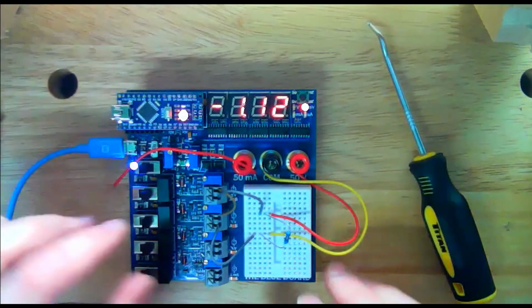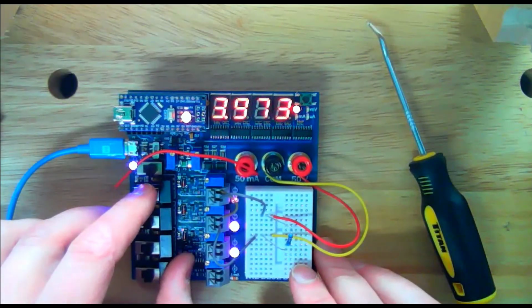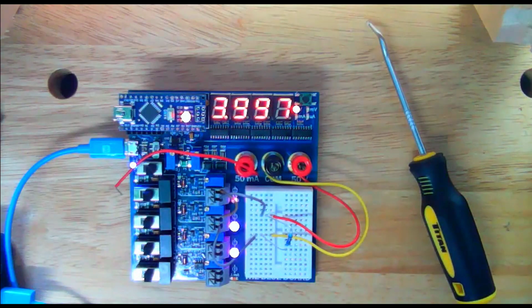Let's energize this and see what voltage we measure. 3.997, that's pretty close to 4. So we have essentially generated a 4-volt supply here by taking a 3-volt supply, connecting it upside down. And again, that's not normally something you can do. That's only because we have 2 quadrant supplies here that are capable of dissipating power.